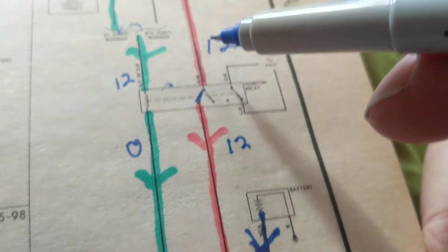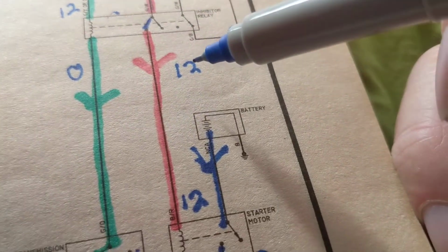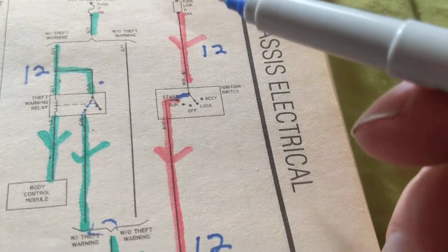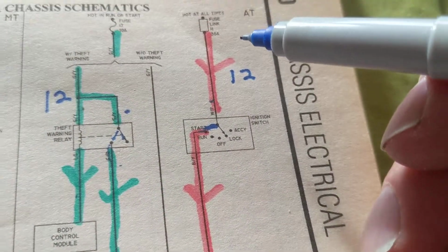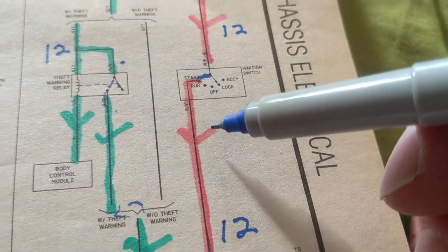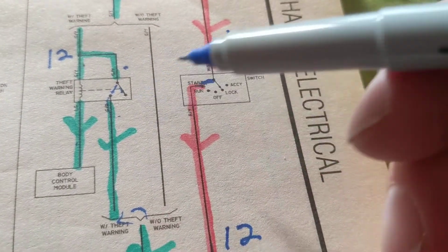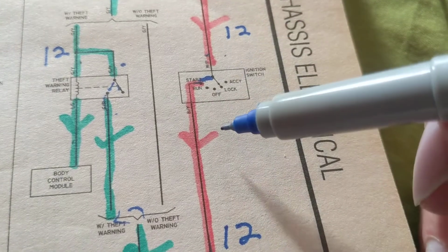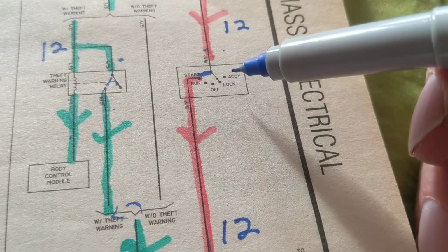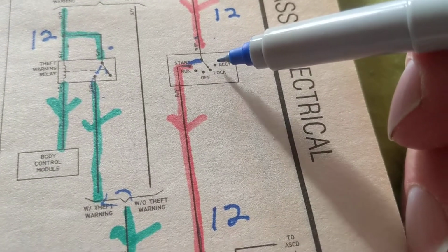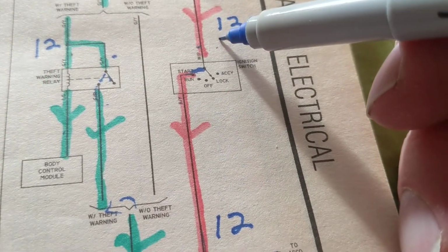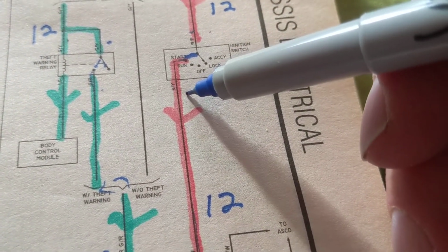Now, notice one thing. I put 12 volts. I put 12 volts. How did I get 12 volts? Well, 12 volts from the battery, of course, right? 12 volts here. Why is this 12 volts? Same principle as here. What's going from here to here? A switch. Does a switch have a lot of resistance? No. Very minimal amount. So therefore we do not lose any voltage from here to here. We started with 12 volts. We're going to output 12 volts.